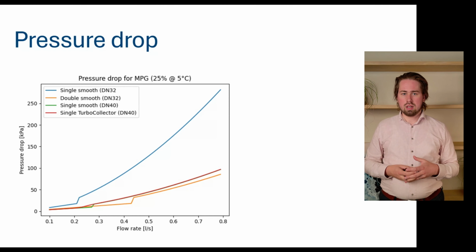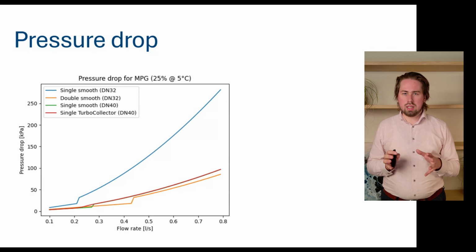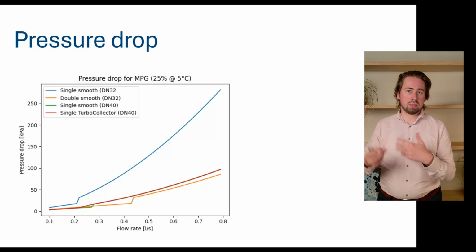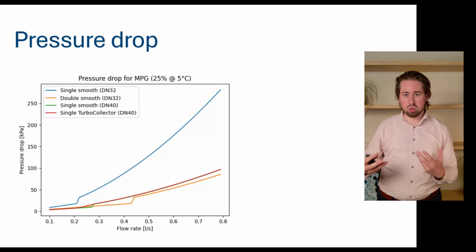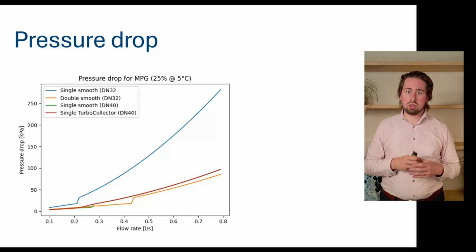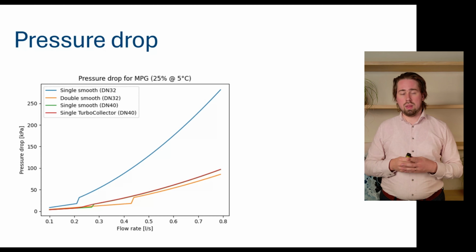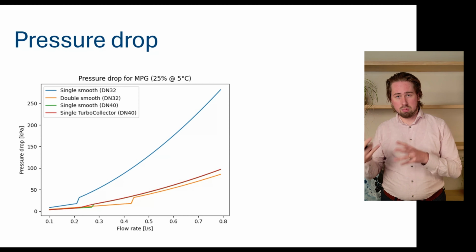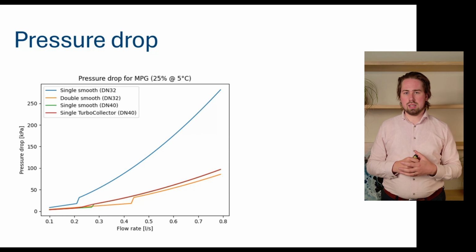So this was what I wanted to say about the TurboCollector: how it was modeled, what computational fluid dynamics is, how we model turbulence in these types of probes, and also to show you what the benefits are when talking about the effective borehole resistance as well as the pressure drop. In the next chapter, we will cover its younger cousin, the MuoviEllipse.